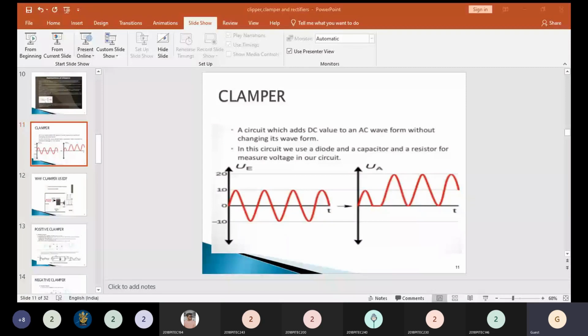Now you can answer this yourself. What is the correct answer? The resistors RF and RL are given, and both are connected in series, so definitely we get the sum of both resistors. So option B is correct. Okay, so the Im value is Vm divided by RF plus RL.